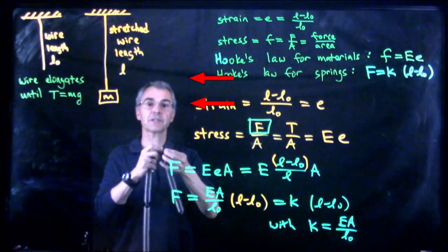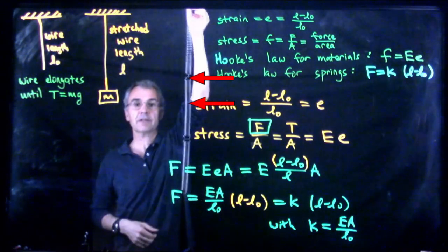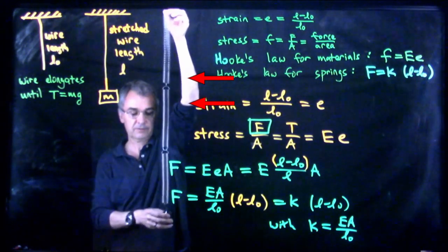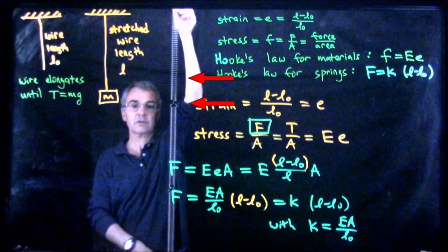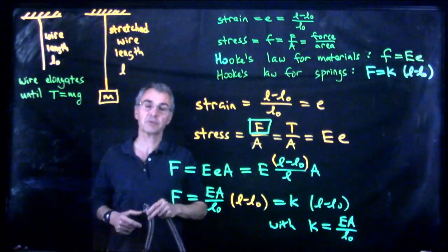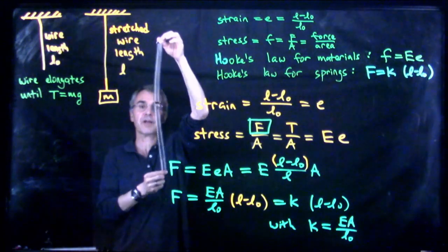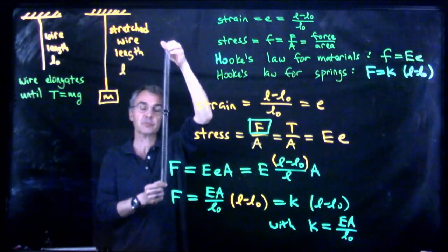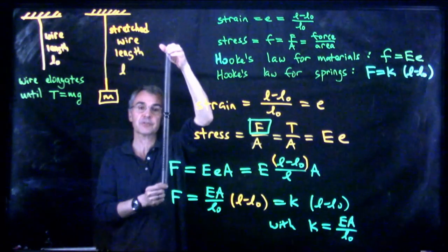Now let's take all 3 of the same springs, connect them end to end, and see how far the bottom stretches when I put that same weight on the end. Oh, it clearly stretches quite a bit more. And if my model is correct, that second stretch should be 3 times as big as the initial stretch. So it turns out if you put 2 identical copies of the same ordinary Hooke's law spring in series, the spring constant is 1/2 of the original spring constant.